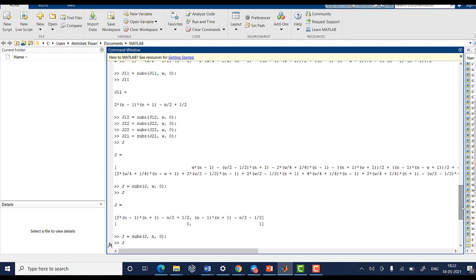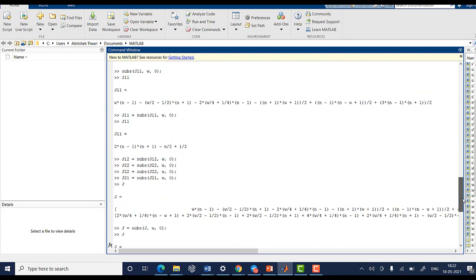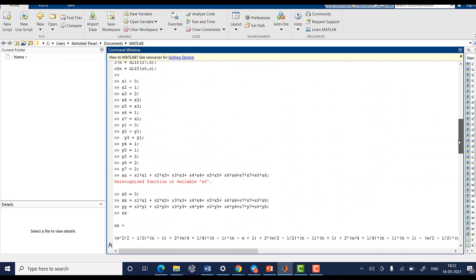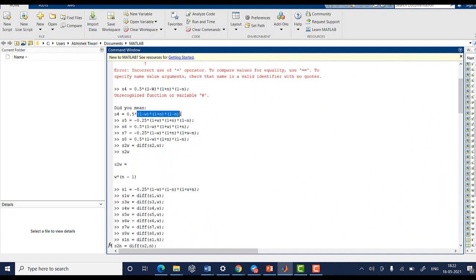So I have done it on paper also. There are fewer mistakes if you multiply the terms before finding the partial derivatives. In the shape function, for instance, here you should multiply this first before doing the differential. When you multiply, some of the terms will cancel out, and then it will also be easier not to do the differential like a chain. You can do the differential piecewise, element wise, and that decreases the amount of mistakes.